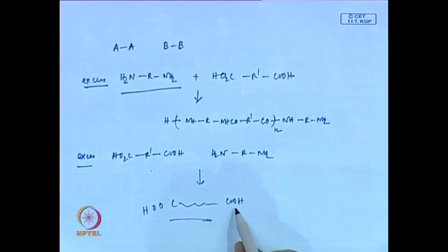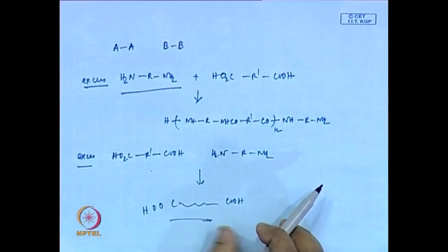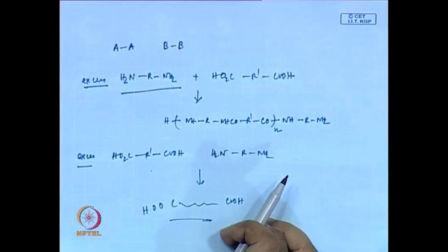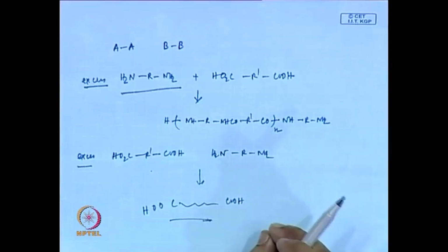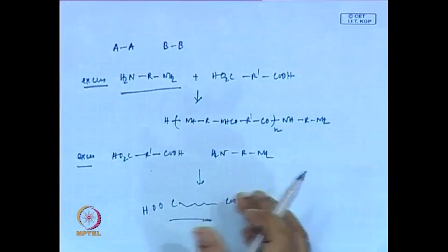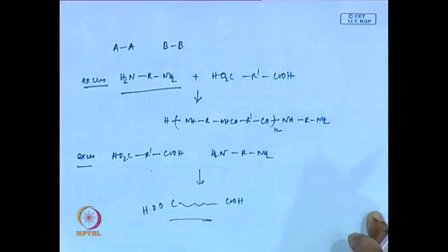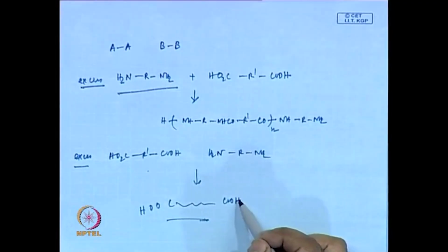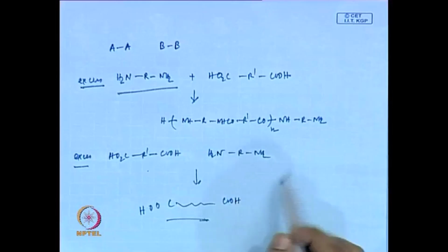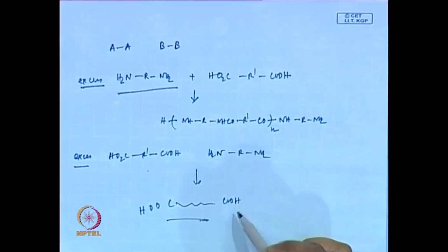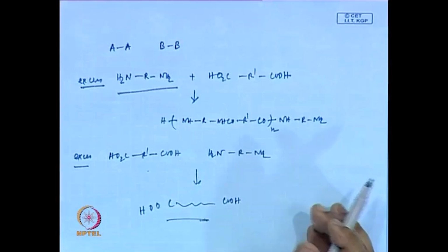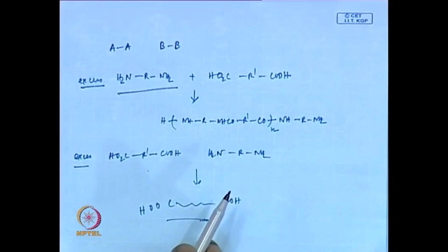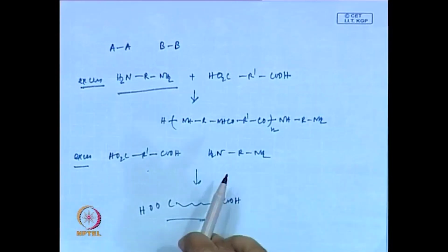Which will ensure that these cannot react by themselves, so that your polymers are virtually dead, unless you have something in the reaction medium further. When you take these polymers out and do a compounding and molding step, unless you are adding something from outside which will be able to react with either of these leftover functional groups, it will stay as it is. It will not react with the functional groups present in the polymers formed itself.